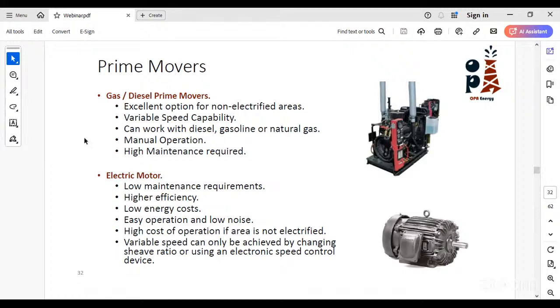And so, of course, if your motor is running at a fixed speed, like for example 1000 RPM, you need in this case sheaves and belts to transfer this motion and reduce the RPM to the best RPM that fits your application and depends on the flow rates you need.